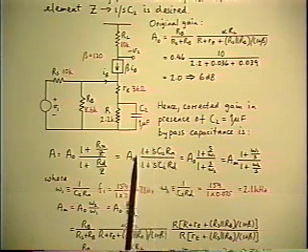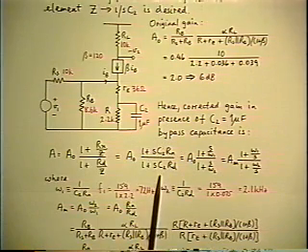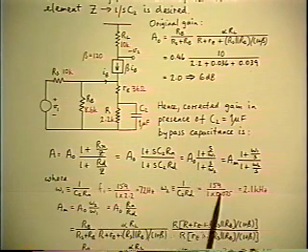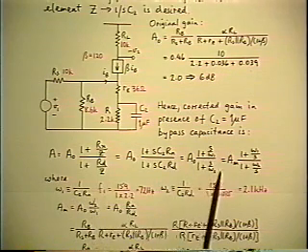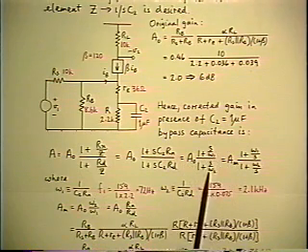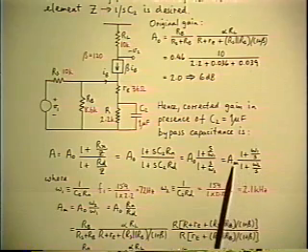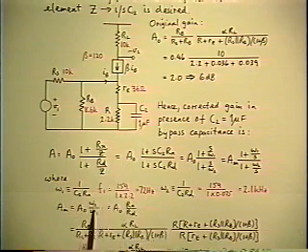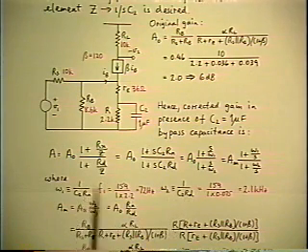And you see the correction factor immediately gives you a pole and a zero. So that defines the zero at omega 1, the pole at omega 2, and there's the definitions. And you have a choice of whether you use the zero frequency gain as reference and the normal pole and zero, or you can invert the pole and the zero and use the high frequency gain as reference. It's interesting to notice that the corner frequencies involve the capacitor that you've added, and the resistance that goes with them is RD for the pole and RN for the zero.